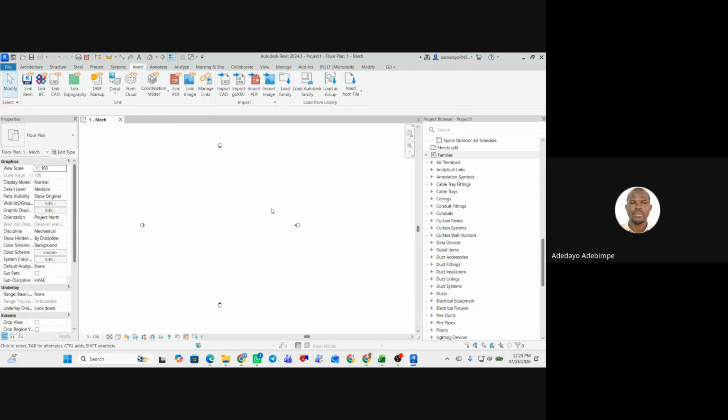Okay, thank you for your question. Good question. So I'll say what I said before, and then build on that. Revit is not backward compatible. If you have done something in 2024, even 2023 cannot open it, not to talk of 2022. Whatever project you do at a particular version, you must use that same version or a higher version to open it. Any lower version cannot open it.